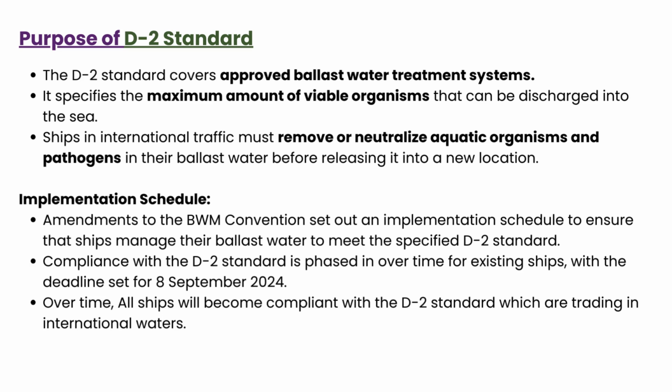You can look into my previous videos, Ballast Water Management Part 1 and Part 2, where we have said that these viable organisms going from one part of the ocean and seas to another are creating great havoc. So the ships in international traffic must remove or neutralize aquatic organisms and pathogens. This is required on all existing ships by 8 September 2024.